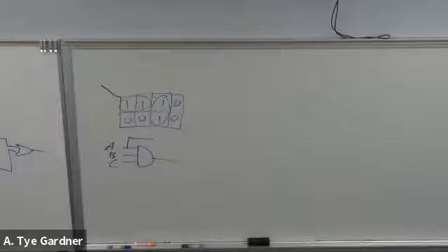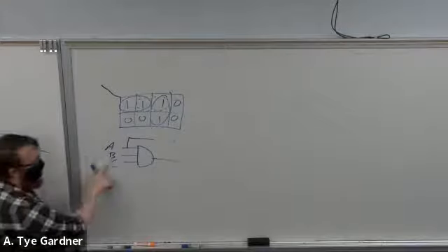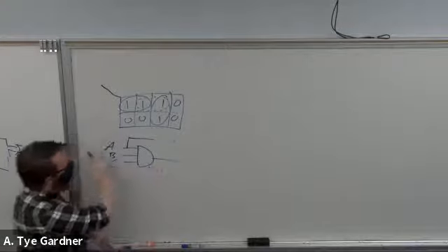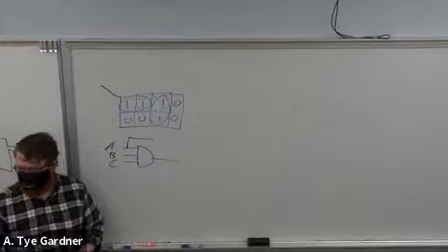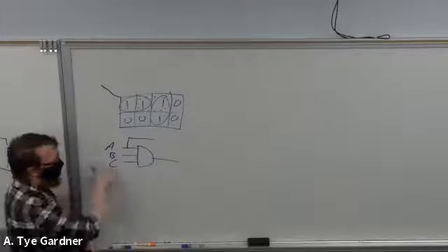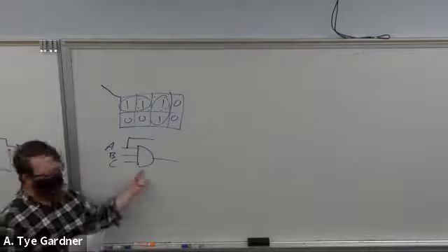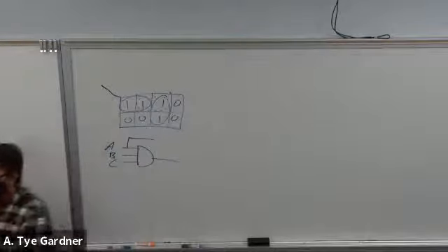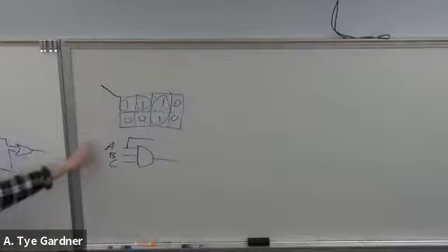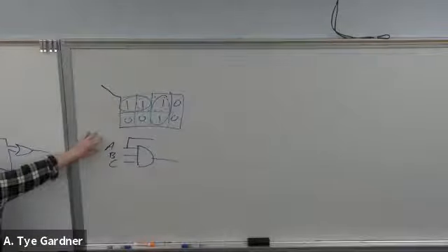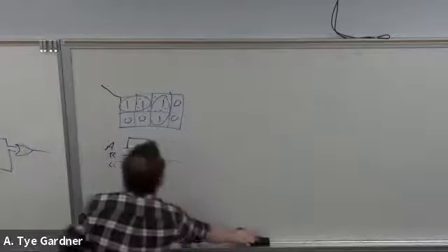I set them both to 1. Because if they're 1, the output of this AND gate can react to A changing. If either of them are 0, A cannot trigger this gate to react. Therefore, it's not primed. It's not ready to respond to my signal of concern. Okay.